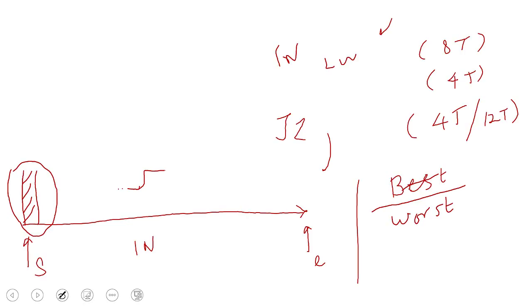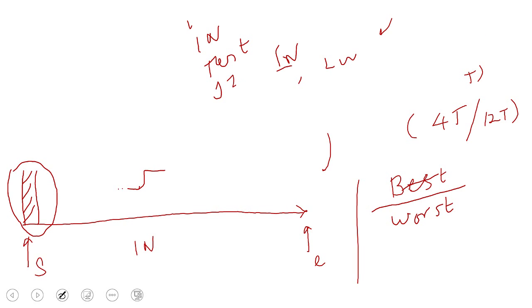Now if you want to catch the next bus, you have to wait in the bus stop until the next bus comes, right? The same way here, there were three instructions, right? The first one was in, then test, and then jump 0. So the in instruction, we wait for 80 cycles, and then we are testing it. That was another 40 cycles. And then the jump 0, this was a failure, so you will wait for 20 cycles.